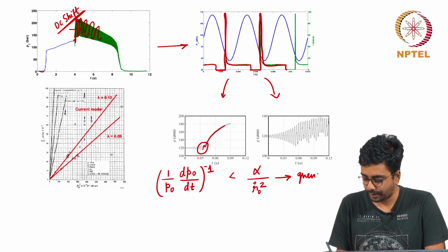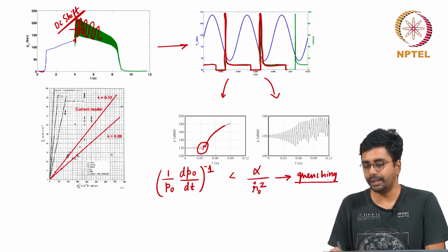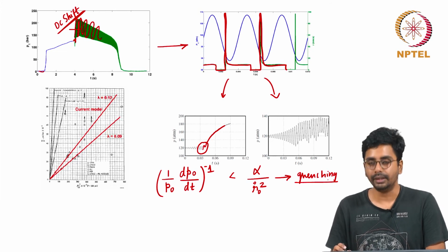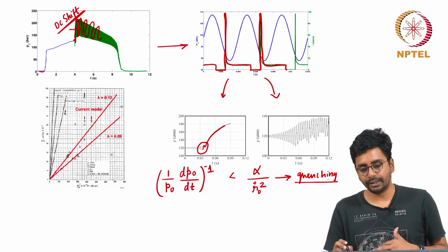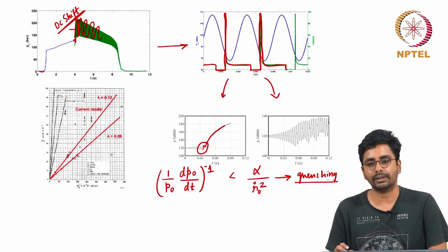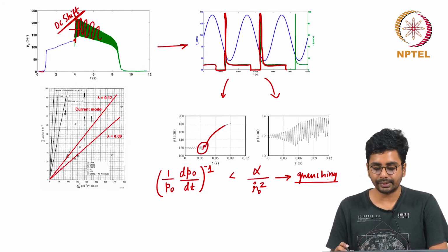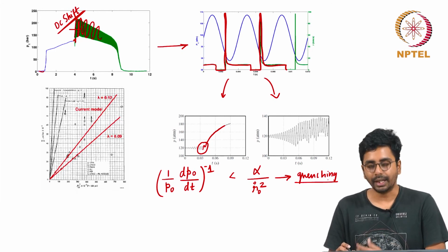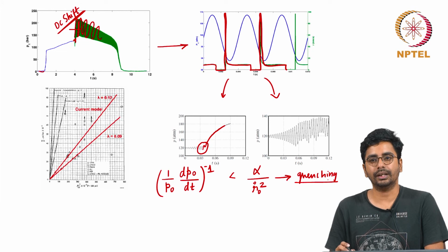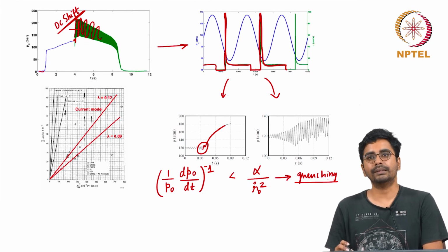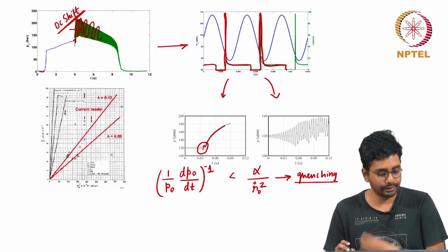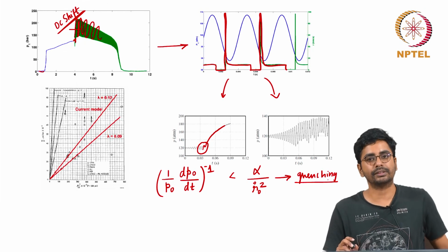This will lead to quenching. If the propellant does not have enough time to adjust to the changes in the gas phase temperature profile, it will quench. In the case of cyclic depressurization pressurization, there is dramatic reignition, because when the propellant quenches, the solid phase still remains at a higher temperature, in the cooked state, and when pressurization happens, establishment of the gas phase flame will simply gasify this entire mass of cooked propellant in one shot, leading to very high burn rates, and that is the origin of the DC shift in solid rocket motors.